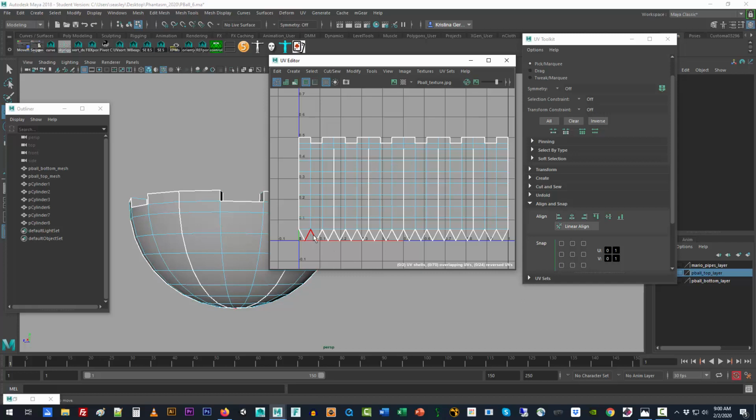So with our edge selection tool still on, come in here and let's do what we did with the sphere earlier, which is to grab these edges and sew them together. And remember that it's Shift S, and you can grab ones out here in space and then go in, and this is me sort of avoiding, on occasion, a pretty irritating little controller. So I'm just grabbing those and pressing Shift S. You can probably do a better job than I did with quickly going through it.